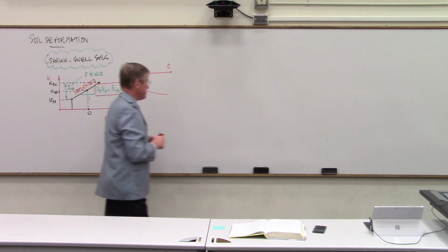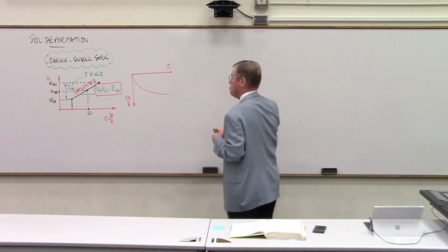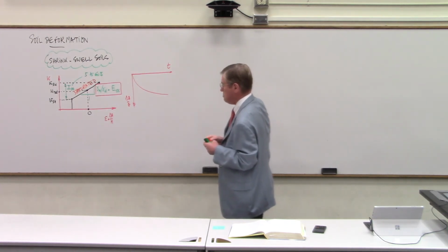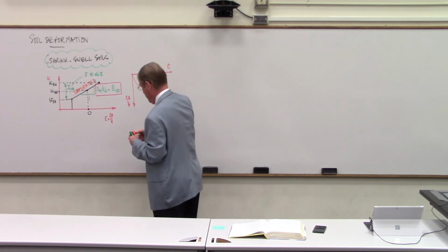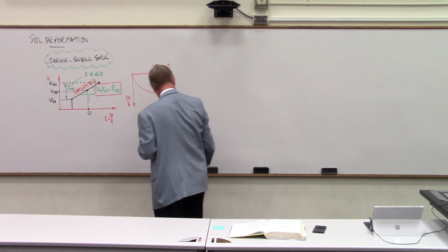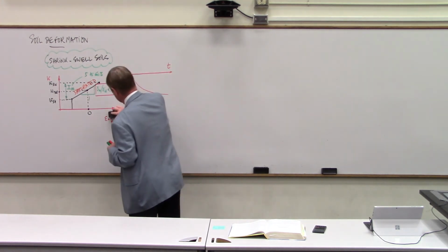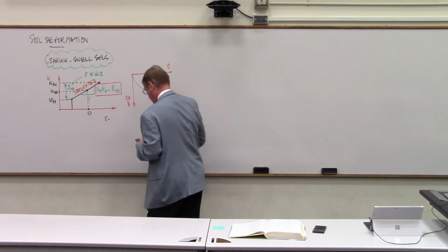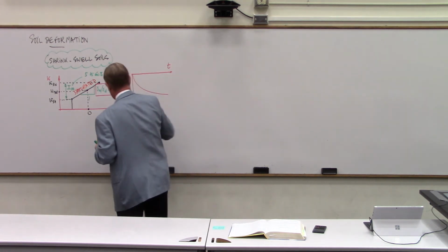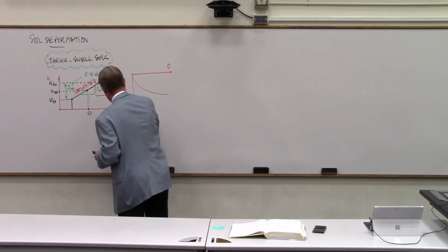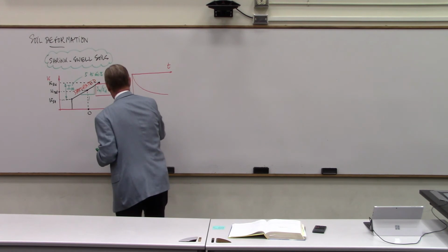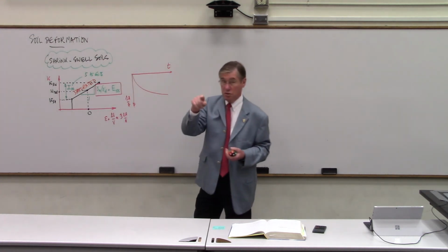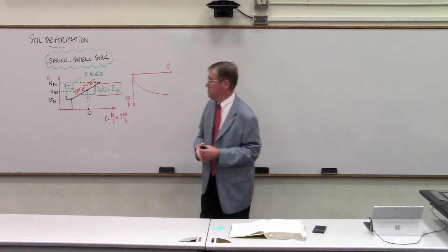All right? Now, if you want to calculate, one thing: this is not correct. I need to correct this. This is delta V over V, not delta H over H. So delta V over V usually is about 3 times delta H over H, because delta H over H is one direction, and delta V is in the 3 directions.